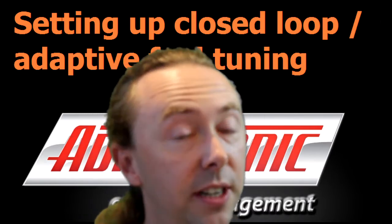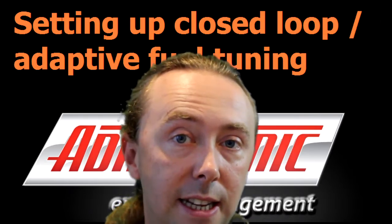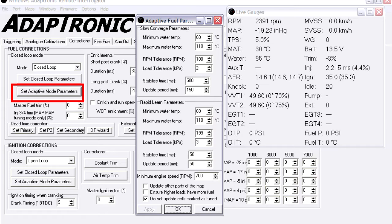So to set up adaptive tuning, you need to do all the steps that I said before for setting up closed loop tuning. Then you can go to the adaptive tuning settings and you can specify how close the engine needs to be to the RPM point in the map and the load point in the map, and how long the engine needs to be at that cell before the ECU will make a change, and then how long it is between changes after that.